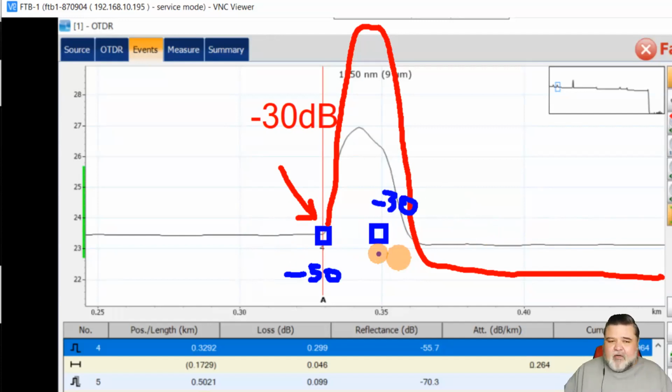And so this is part of the limitations of the OTDR and how to compensate for that. This is one of the ways that you can compensate for the OTDR: by reducing the pulse width and taking another look at it. And so that's how these two tie together.